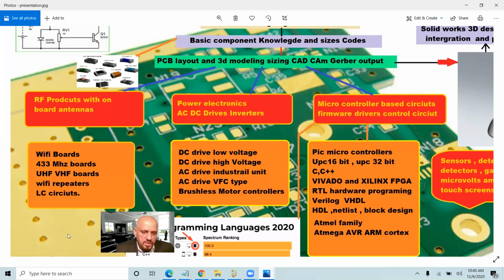The problem was when we connect our laptop with the mains line, it was generating so much noise because the system was getting the feedback from the board into our computer. That line, which is basically 5 volts, got polluted because the adapter, which is basically supplying power to the laptop, was not right. So understand, experience has got no shortcut. These things do come.